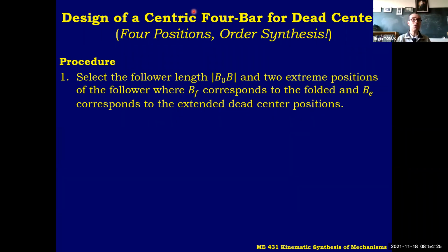But if the machine is doing work in moving one side, and if it's idle going back, you would like to reduce the idle time. In that case, centric 4-bar is the worst design, because its idle time is equal to its working time, okay? So you would require a time ratio that's different than 1. It would do the forward stroke slow and backward stroke fast, okay? Which, if time permits, we will discuss later. So know the restrictions of this.